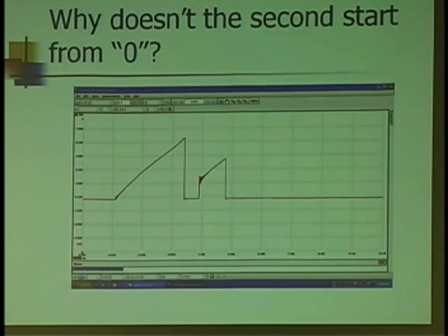Could I use that bit of knowledge to diagnose some of Ford's COP coils? What if I saw that second pattern starting off at 0? Would that be a problem? Sure, there wasn't enough energy in the first go-round. What happens with those coils? Don't they leak internally in the secondary? Sure they do. What causes that?